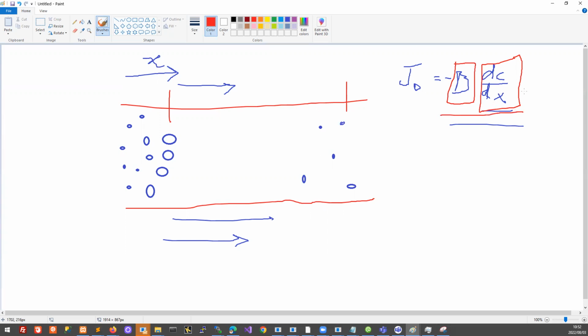So we can actually estimate the molar flux due to diffusion, right? So we've got the diffusion flux, and then we can estimate, if we were to choose a certain cross section, so let's say we stuck in a 2 centimeter pipe over here, some pipe that is maybe withdrawing material, then we can estimate how much of this component is going to diffuse into this interface here.